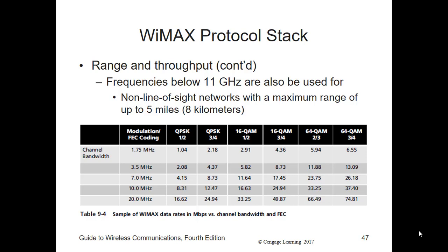One reason is that the WiMAX channel bandwidth is shared among the base station and subscriber stations, and therefore the number of simultaneous devices actively communicating affects the maximum throughput at any given time. Another reason for lower throughput is that some of the overhead, such as the MAC layer framing, is not included in the actual rate calculations.